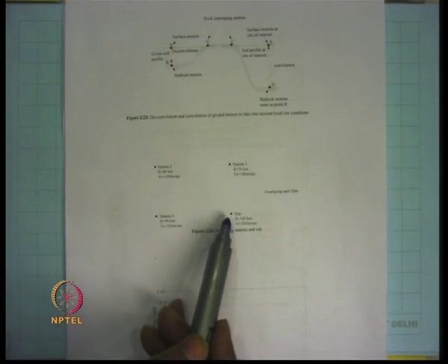With the help of that information and the particular attenuation law that is valid for the region, we perform the calculations in order to obtain the site specific spectrum at this particular site.